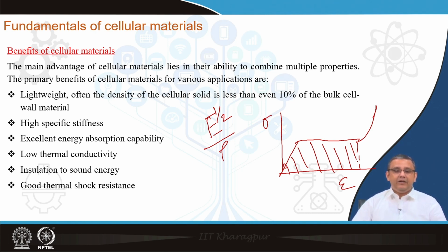But a cellular ceramic with a large amount of air in the material is very good in thermal shock resistance, because the large amount of void does not let the crack propagate in a catastrophic manner, and the material can sustain for a longer period over a large temperature range.